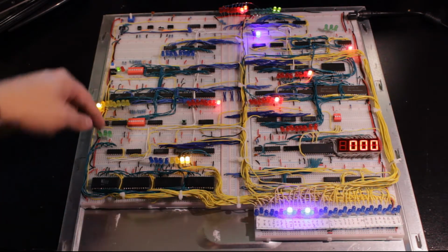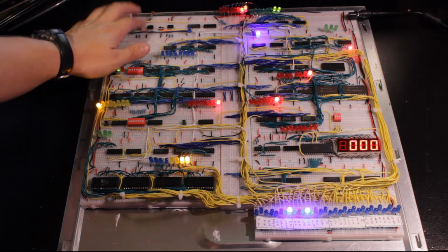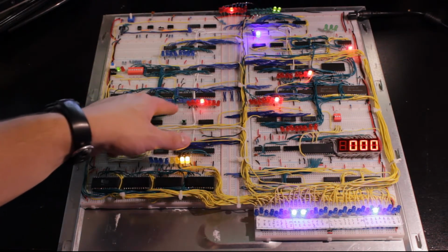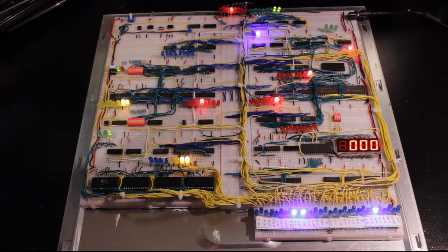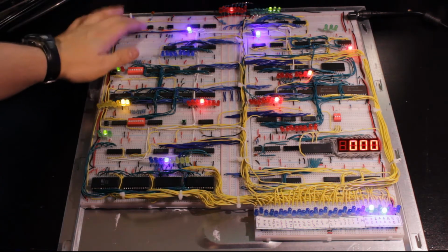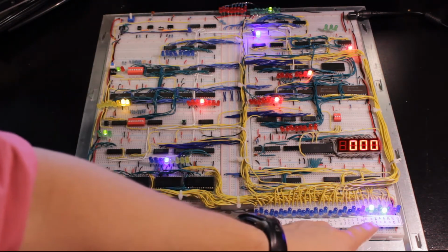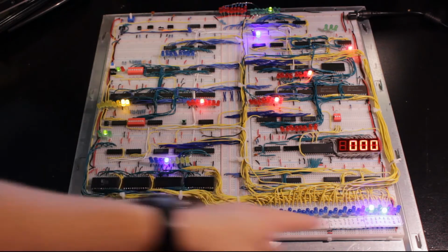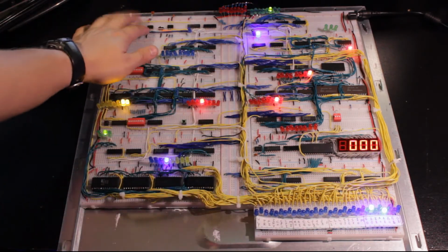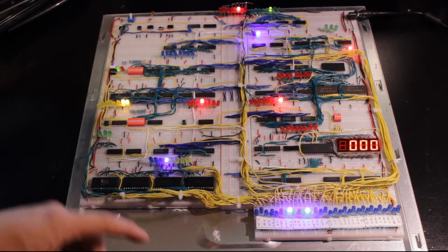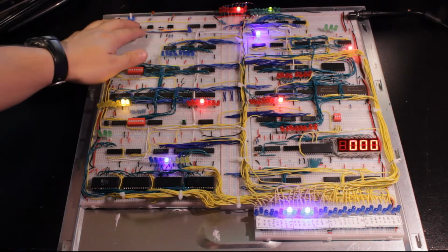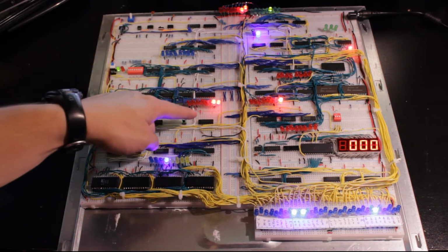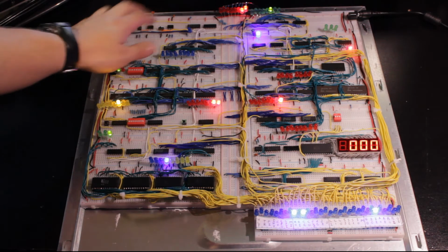So now we're doing a fetch cycle, memory in, counter out. We're going to go to address 3 and get the next instruction, which is a 0x10 for a load A immediate value of 0. So what that's going to do is say instruction register out, puts a 0 on the bus, A register in, and it's going to put 0 in the A register. And then we're doing a fetch cycle again, and we're going to get the next instruction, which is 0x03 for a store A.